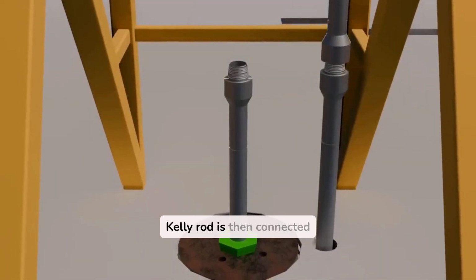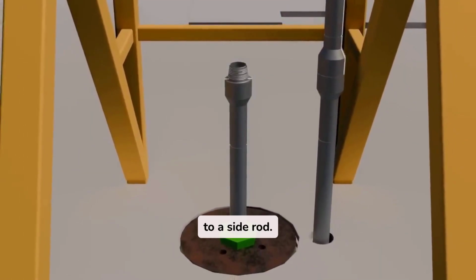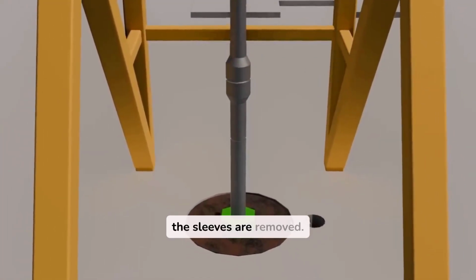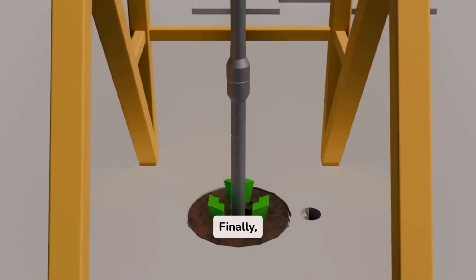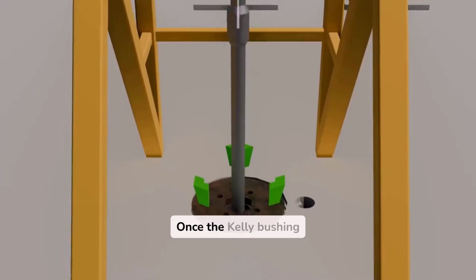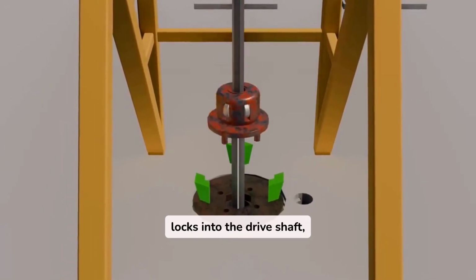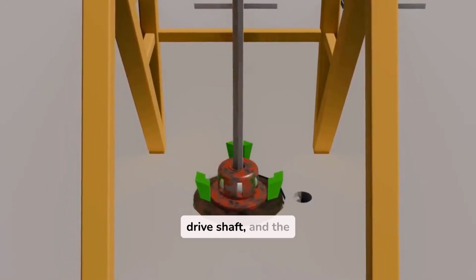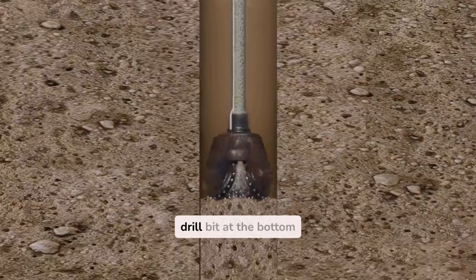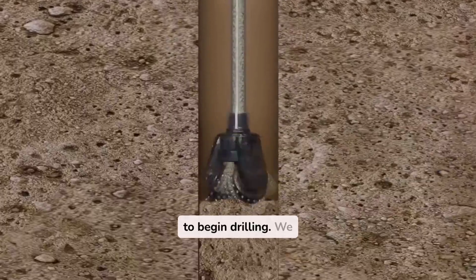The Kelly rod is then connected to a side rod. After that, the Kelly rod is reconnected to the string, and the sleeves are removed. Finally, the entire assembly is lowered back into the borehole. Once the Kelly bushing locks into the drive shaft, power is applied to the drive shaft, and the entire drill string starts rotating, enabling the drill bit at the bottom to begin drilling.